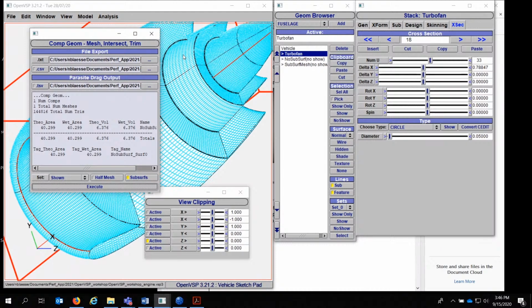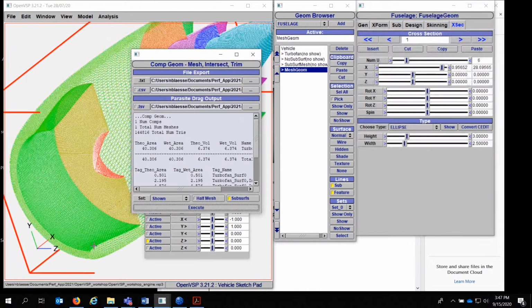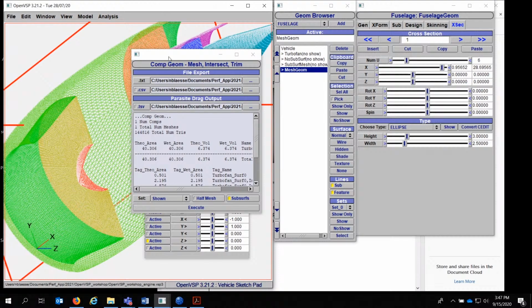When I ran through this inviscidly, like I said, I just eyeballed most of this geometry. It's more or less right, and every engine looks more or less like this. The diameters will change, the max thickness will change, the length to inlet diameter will change, but fundamentally it's the same. When I ran it viscously, I did get separation coming off of this inlet lip because it wasn't designed terribly well. It was just eyeballed, and inviscid calculators don't care. There's no separation. Viscous calculators do care.